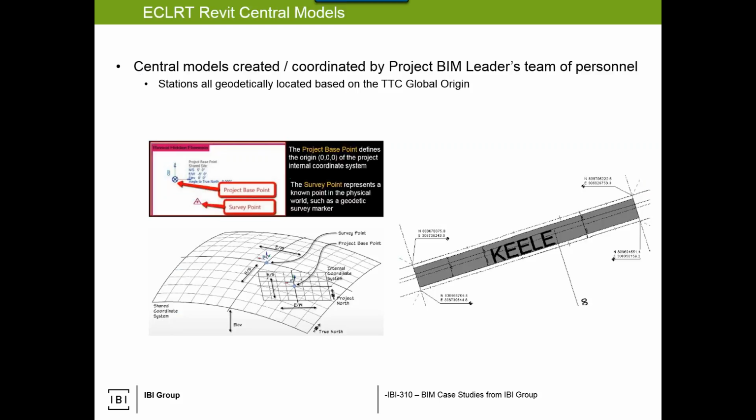And this is just a snap from the Navigator. One of the hard parts with projects like this one was to actually geospatially coordinate the information. So with every single station, there was a development of control points that aligned it to the overall civil base mapping that laid out the rail network, the rail control points, and there's that synergy back and forth between the Revit building model and the overall civil site rail model, if you will.